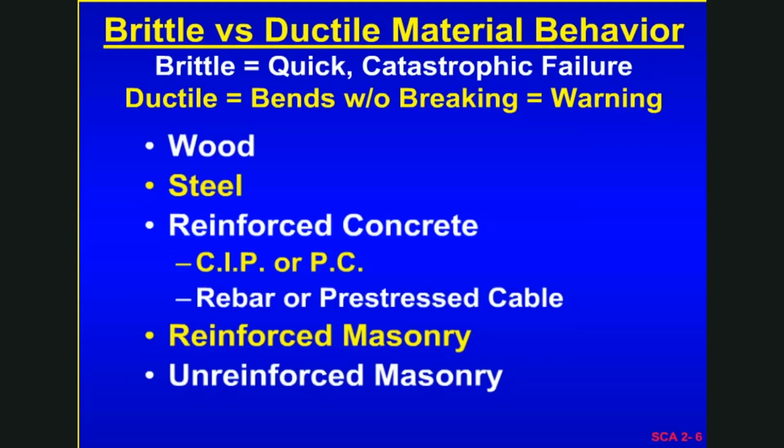The reinforcing, that is the steel that is reinforcing concrete, taking those tension forces we talked about earlier, may be the reinforced steel or deformed bars, which are called rebar, as you probably know, or it could be cable that is pre-stressed, a very high-strength cable that's pre-stressed within the concrete. In precast concrete, the cable may be stressed ahead of time, and then the concrete is cast around it, which still makes a fairly good structure bonded together.